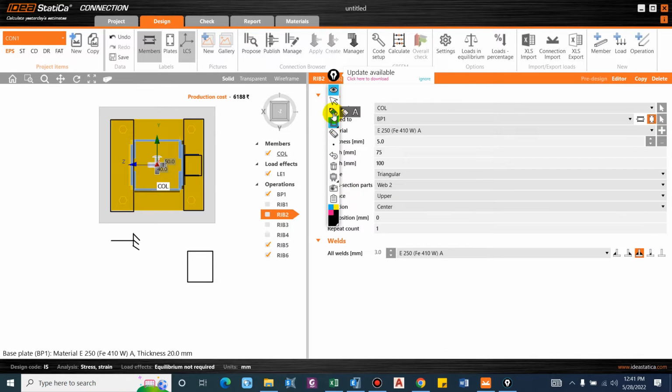So now it is fixed at this side, this is fixed at this side due to stiffeners, and we know the load transfer mechanism for this type of slabs. So it will be something like this. So the triangular portion over here will be taken by this, the triangular portion will be taken by this, the triangular portion, this will be resisted or transferred to this stiffener.